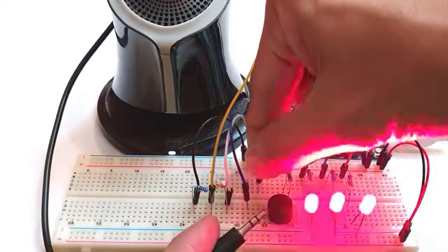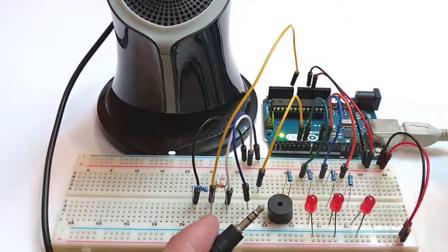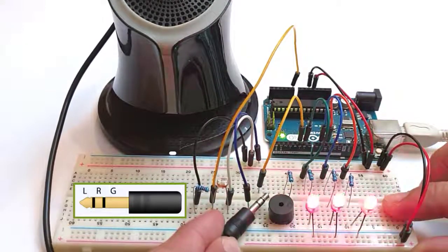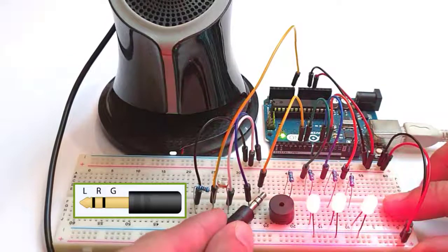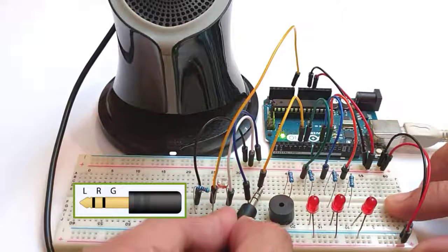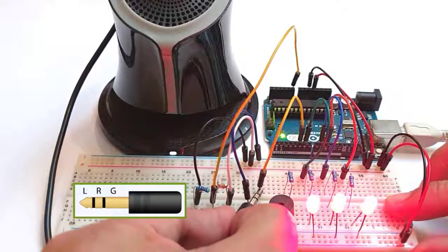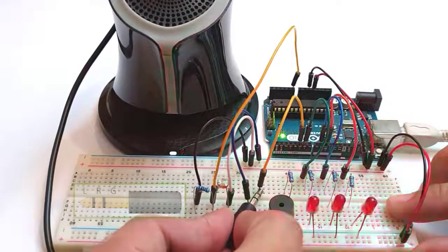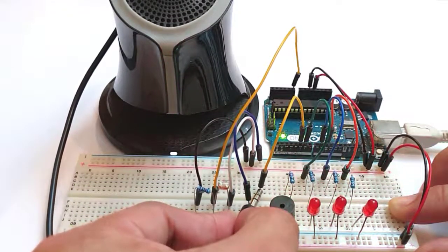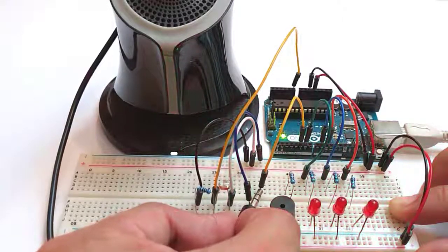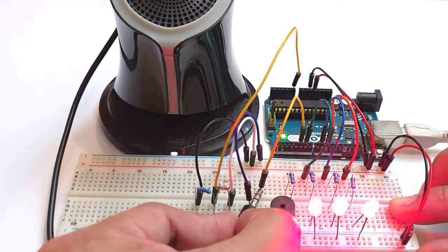In your 3.5mm TRS audio jack, this is the ground, the middle is the right channel, and the tip is the left channel of your speaker. So, what I'm going to do is to connect this ground of the TRS jack to the ground of the board, and pin 5 of the board to the tip of this TRS jack. And as simple as that, we have amplified our Super Mario tone.